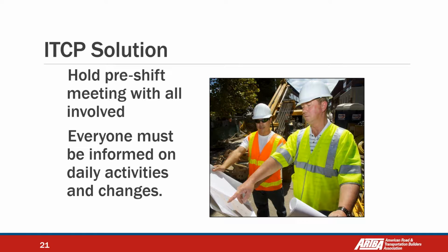Of course, it's going to require some additional coordination, but it is the nature of an internal traffic control plan to have coordination with the company, because they can use this picture of the diagram to send this to all the other stakeholders. For example, we know that somebody from the DOT is going to visit the work zone today. It's important to have a diagram helping them to recognize where is the access zone, where is the parking area, where the trucks are going to park or wait to deliver materials, to prevent confusion.